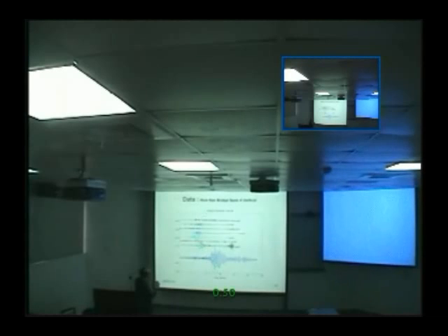All the other trucks were fine. So the heavier truck indeed caused the bridge to broaden. And that broadening, based on our analysis, and only on our analysis, shows nonlinear behavior. The bridge operation has already gotten into the nonlinear range.